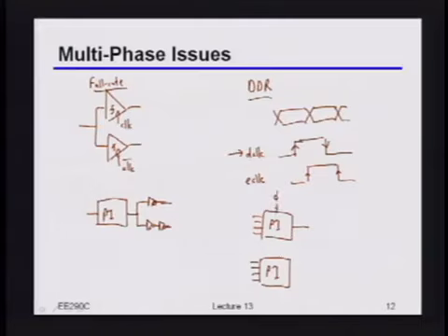So if let's say this is some phi, I can make this phi plus 90, right? And then indeed, I'll get 2 output clocks, which at least nominally would be separated by 90 degrees. Okay, so this works. By the way, there's some people that do what's called QDR, which means the clock is 4 times slower than data.